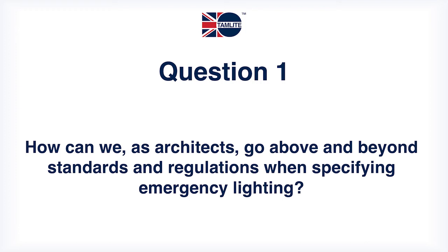Right, yeah, I mean it's a very good question, of course, because I touched on it a couple of times throughout the presentation, talking about the standard having one measure. For instance, BS 5266 talks about minimum requirement of 1 hour duration for emergency battery life within emergency luminaires.